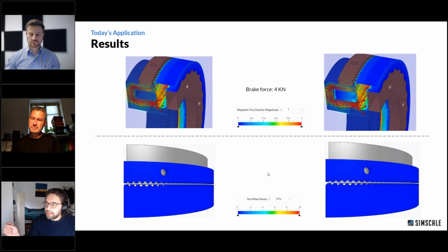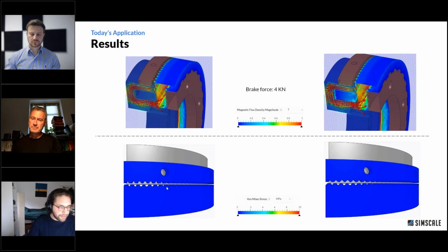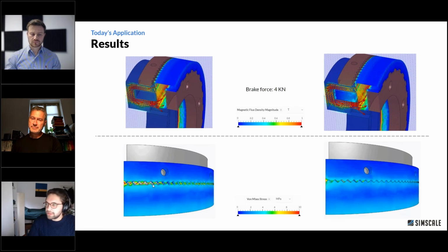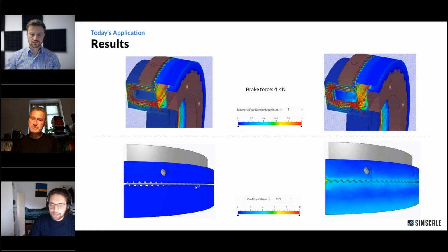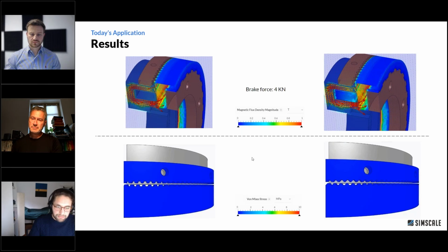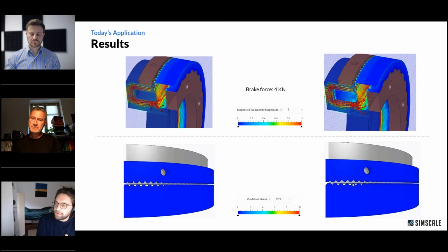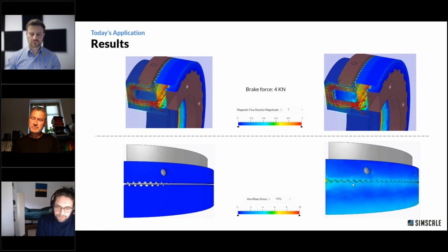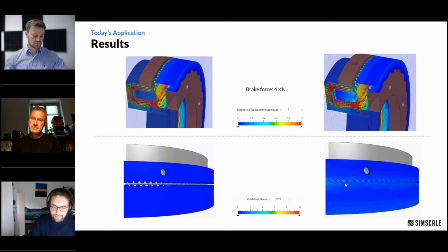Now, as I mentioned at the beginning, there was a 2-degree misalignment in the design between these two. For the standard toothing, we see that because of this misalignment, we have high stresses being generated at the corners that might make this a suboptimal design for a particular application. Such a problem is mitigated with the sawtoothing, which allows for more area for the interlocking. So this allows for a better torque interlocking mechanism between those two.